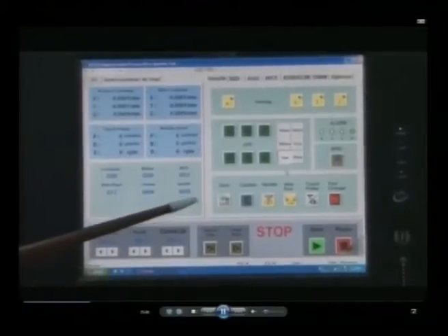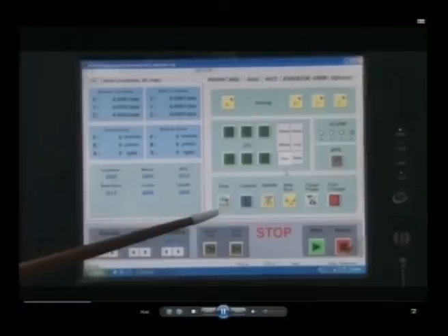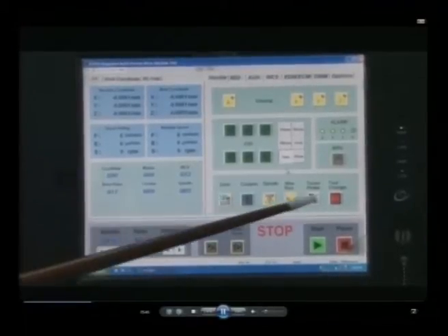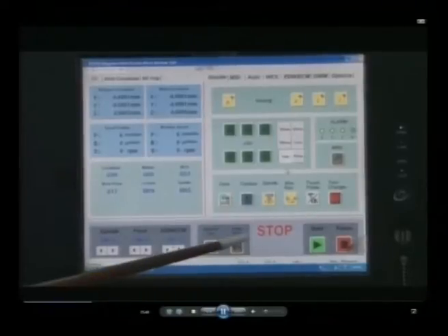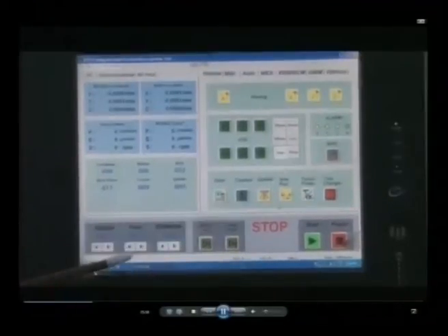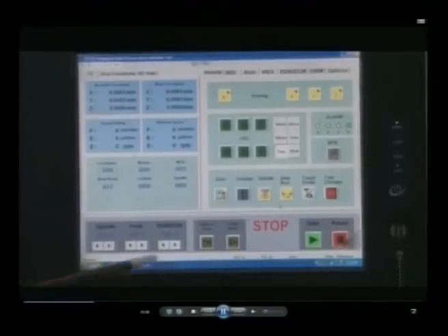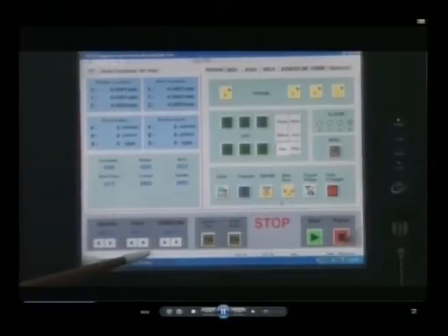The fourth command in the front panel has 6 options. All these are 6 different switches which perform 6 different operations. These 3 options are used to change the value of speed, feed or EDM feed during operations. That is, during execution of a program, the speed, the feed or the EDM can be varied by a certain percentage.